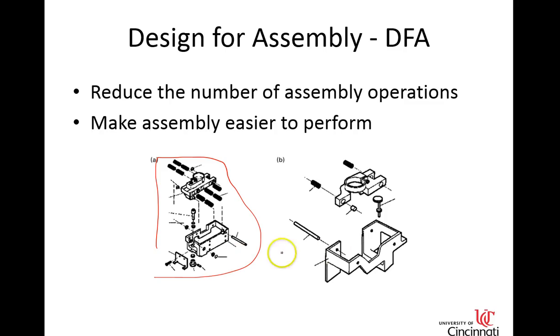So we've eliminated all these little nuts and bolts and dials that probably aren't going to move relative to one another and may actually just be assembled and made rigid and turned into one component. In other words, combining. So we reduce all those parts down to this limited number of parts. Easier to assemble, faster to assemble, less parts to keep track of.